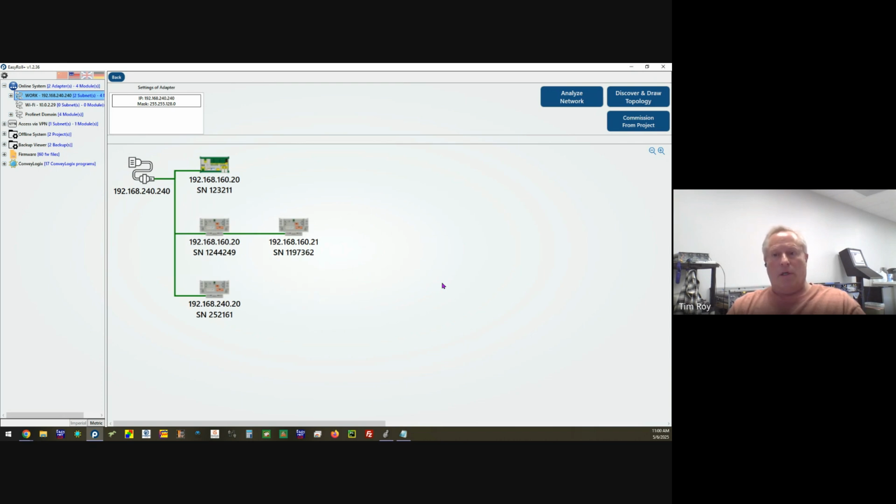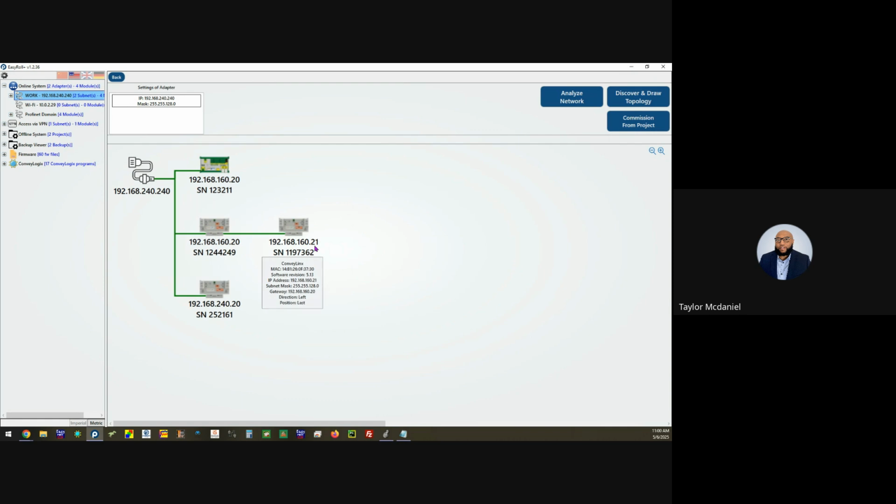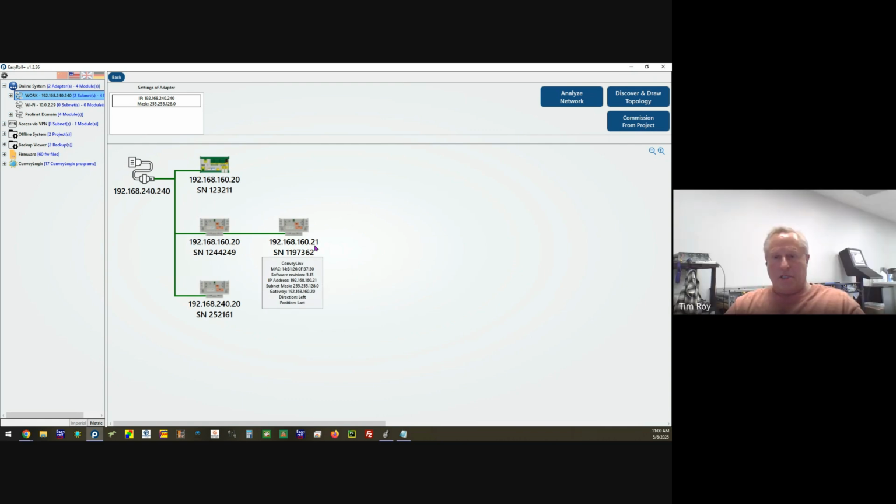The next card looks at the IP address. It increments the 4th octet by 1. Thus, I became 21. I keep the subnet mask. I keep the configuration ID. Then I look at my right port. Do I have another connection? If I had another connection, it would pass the data. The next card would become .22.